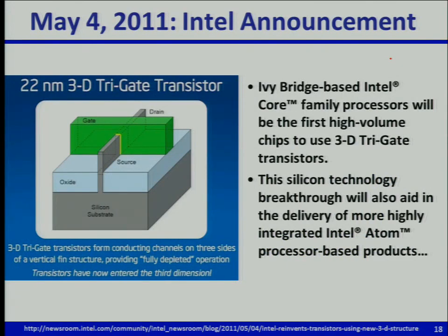So as I mentioned, Intel announced the FinFET in 2011. Notice they decided to use not an SOI, but a silicon substrate because it's lower cost for manufacturing. But this means that, so this is the fin width here, and here's the fin height, that determines the transistor width. But notice they have to etch maybe 50 nanometers or so more deeply to form the isolation oxide, the oxide that isolates one transistor from another. And then in the silicon, to prevent leakage from flowing between the source and drain through this silicon fin, they have to dope the fin very heavily underneath here.